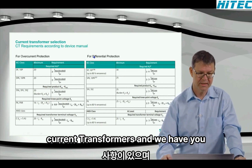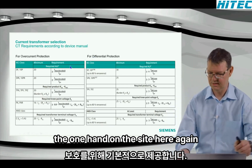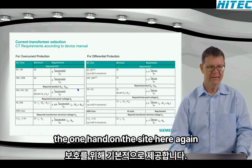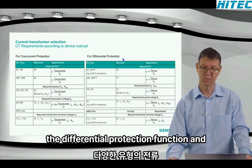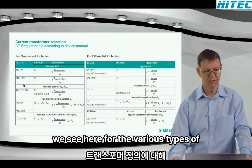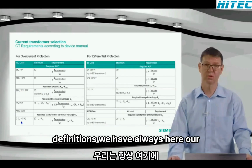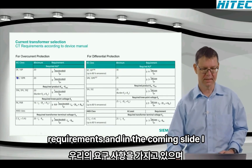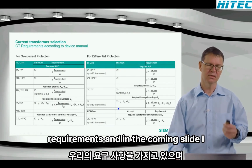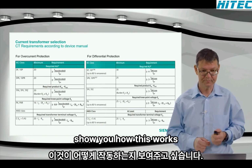And we have here basically for the motor protection on the one hand, the overcurrent protection function and the differential protection function. And we see here for the various types of current transformer definitions, we have always our requirements. And in the coming slides, I would like just to make an example and show you how this works.